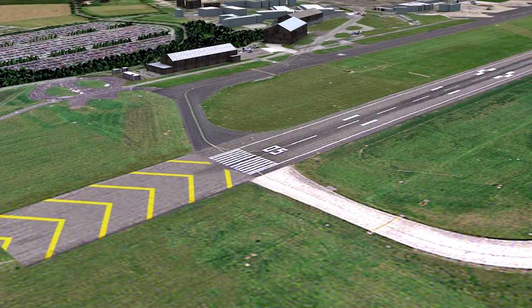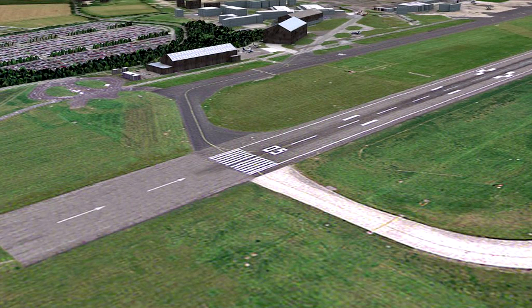To help the pilot recognize the stopway, it should be distinctly marked, as shown here. As a rule, the takeoff or landing run should always be started or stopped at the threshold. There is one exception to this rule. If a pilot sees the runway markings shown here before the threshold, then he may use this marked portion of the runway for the initial takeoff run, but it must not be used for any other purpose.